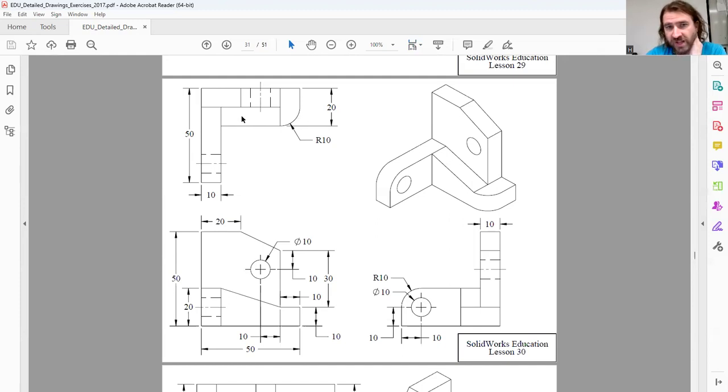If you extrude this rectangle here up, you need to chamfer it probably before you extrude this up fully, because it's going to join those bodies together. And if we have time in this video, I'll show you an example of what I mean by that. But there's going to be a little bit of a trick to get that chamfer to be correct. And so there's going to be a lot of additional things going on here. Obviously, we have an incredibly busy front view of our sketch here. There's a lot of information here.